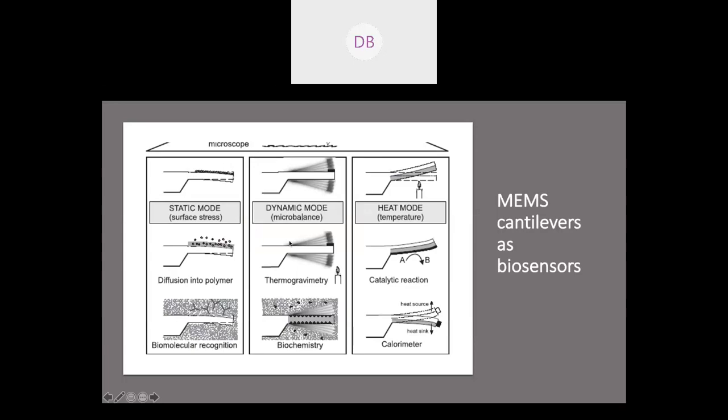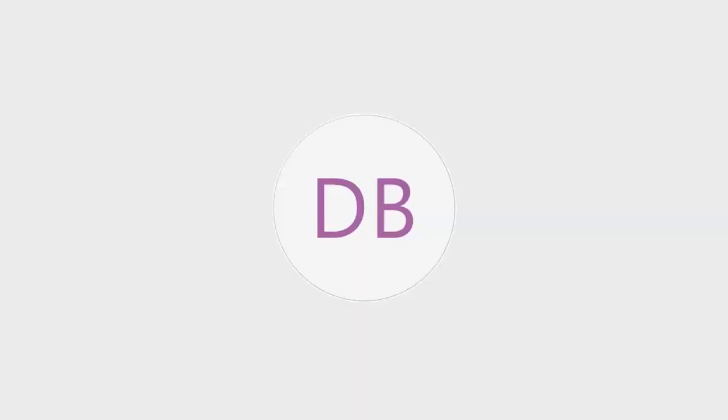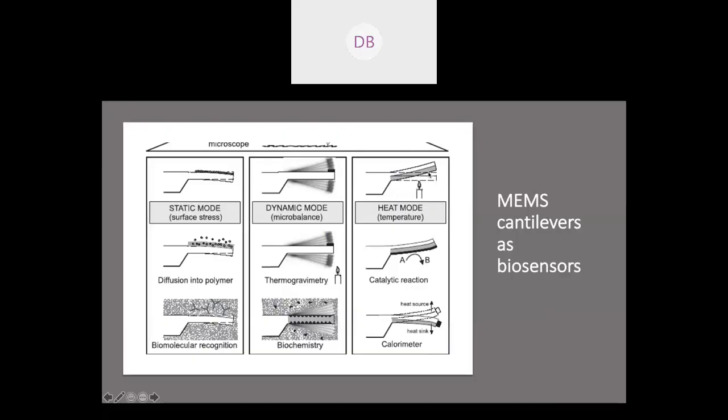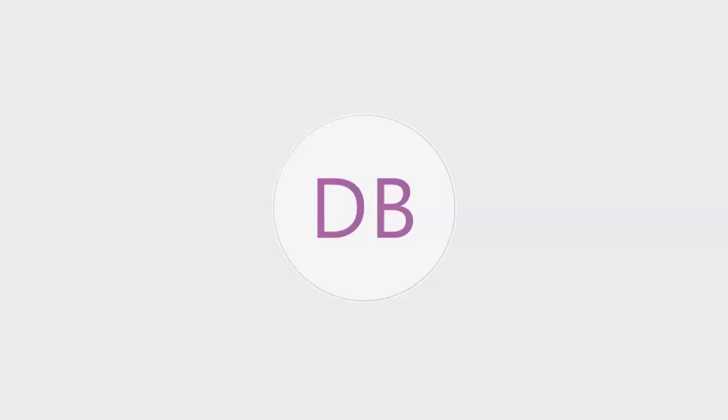Generally, we are all aware of bimetallic strips, the principle which is used in refrigerators or AC machines, where as the temperature is changing, one metal will have a larger thermal coefficient of expansion, the other will have a lesser thermal coefficient of expansion. So when the temperature is changing, one will expand more than the other. So obviously, it will lose contact with the power supply and it will stop. The cooling process in the refrigerator or the AC machine will stop. Again, when the temperature increases, slowly it will contract, and again it will come in contact with the power supply, and again it will restart. So that is the automation process that is used.